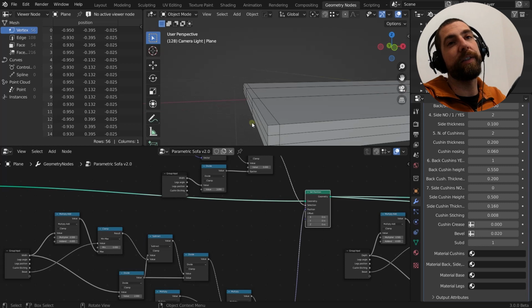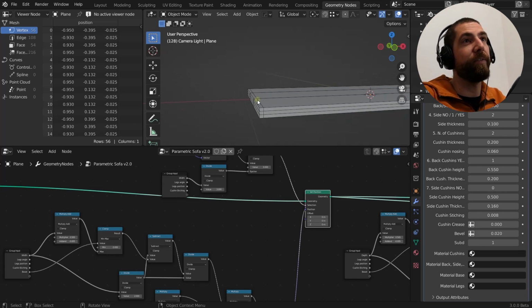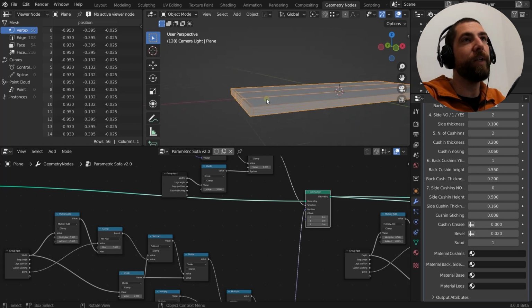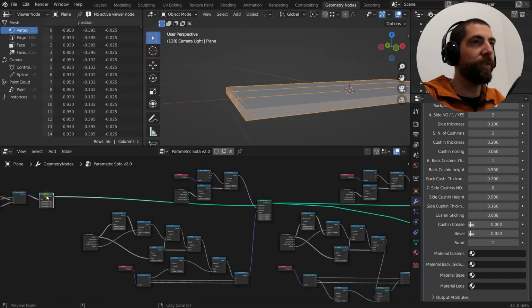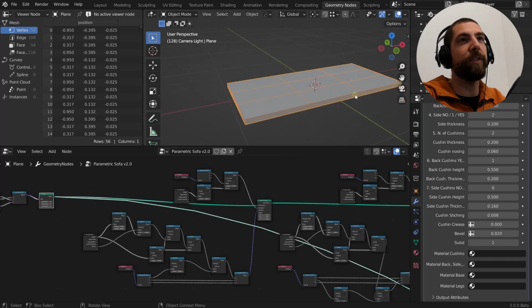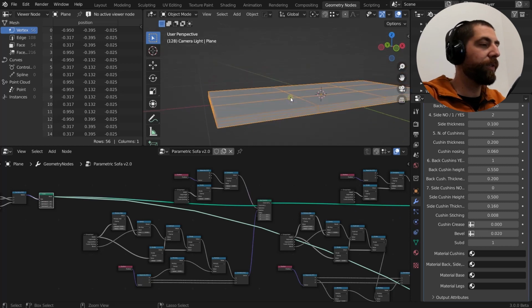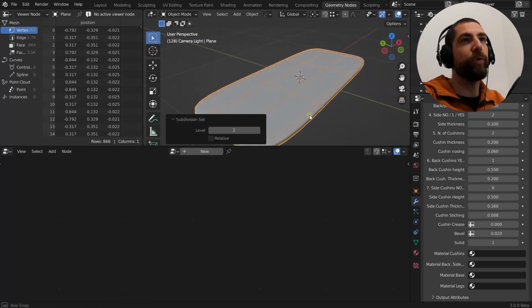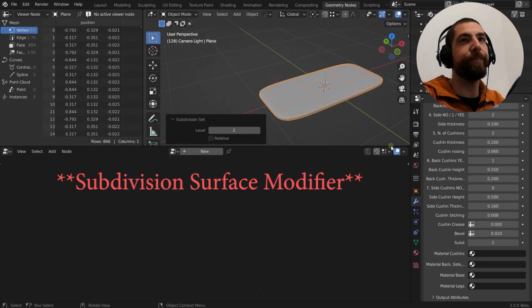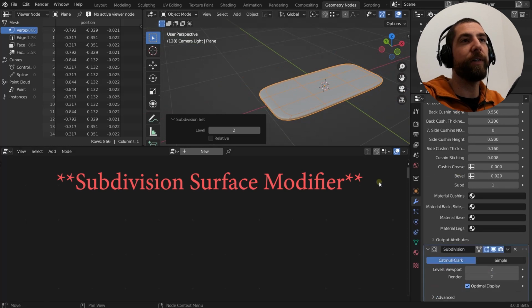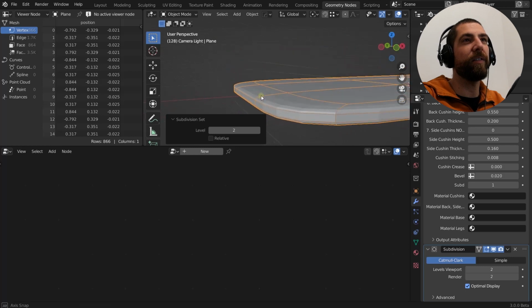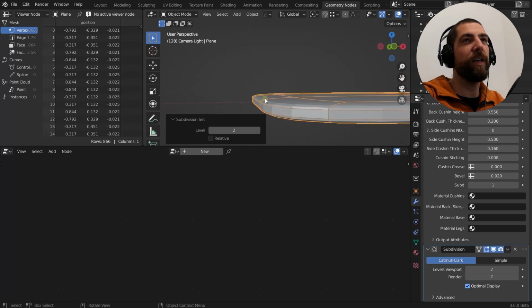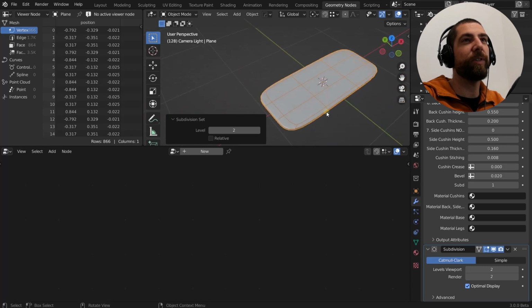So we need to find creative ways to create a bevel, because if I was, for example, from this node, where the loop cuts are here, to press Ctrl 2 to just add a bevel modifier, you see that I am beveling quite well on this side, but here it's a real mess.